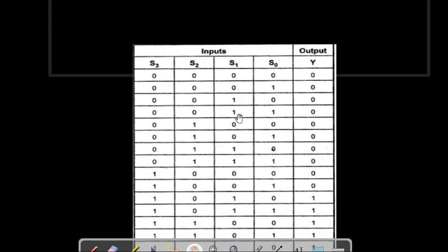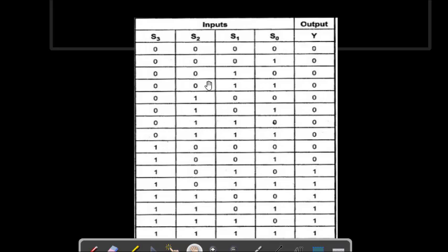So we have to design that logic. Here in the first case, we see the sum goes from here up to here, 9. So 9 is 1001, so up to here the output should be 0, because we don't need to add anything.